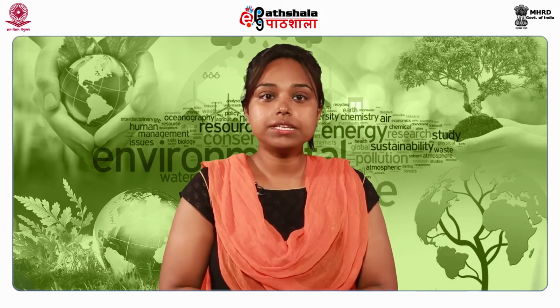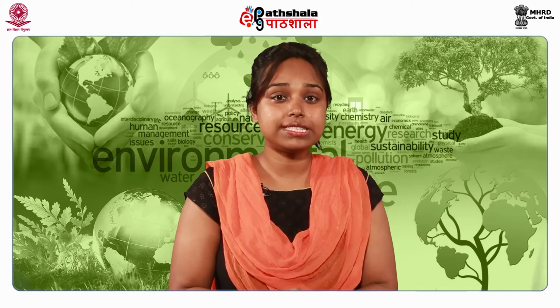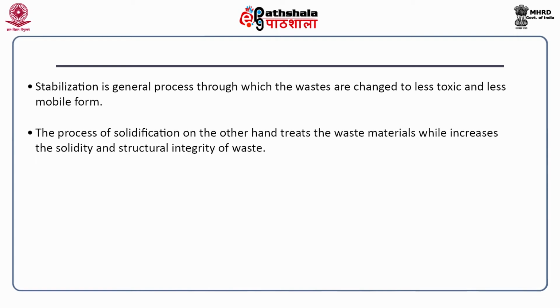The process helps in reducing the surface area and mass of waste and also restricts the solubility of hazardous substances in the waste. Stabilization is a general process through which the waste is changed to a less toxic and less mobile form. The process of solidification, on the other hand, treats the waste material while increasing the solidity and structural integrity of the waste.